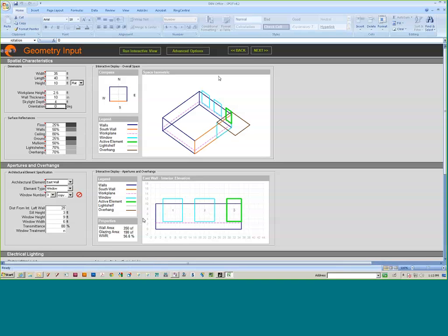Okay. But one question I have for you, Casey, is the windows are taller than the space? They are. It's kind of odd. The grid ends about 6-8 inches from the wall, and the windows continue up another foot to 2 feet above that point. So, for our daylighting purposes, I would consider trimming the window at the top of the ceiling, because that's our enclosed volume for daylighting calculations. Okay. So you don't have to change it now, but it's just a tip. Oh, very good. Yeah, essentially it'd just be a complete light shelf, so it would get cut off anyway. Right.